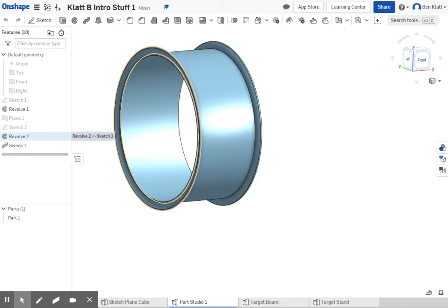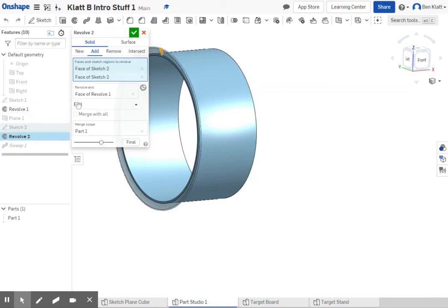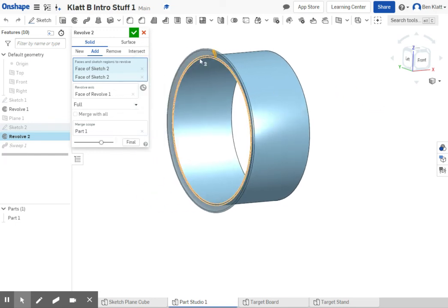You can actually go back and edit that by double clicking, and selecting what you did and removing it or altering it. So right now I had a couple of faces that I revolved around. If I had done the other one, I could have removed the faces of the other side because you were supposed to do that as a sweep.